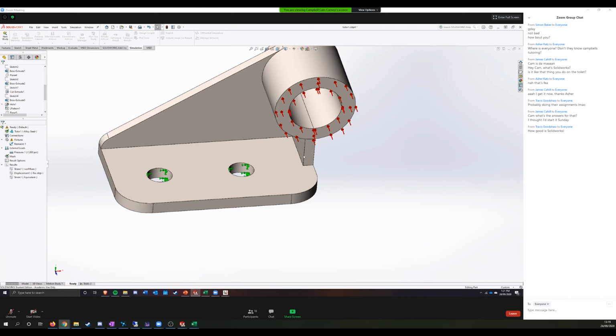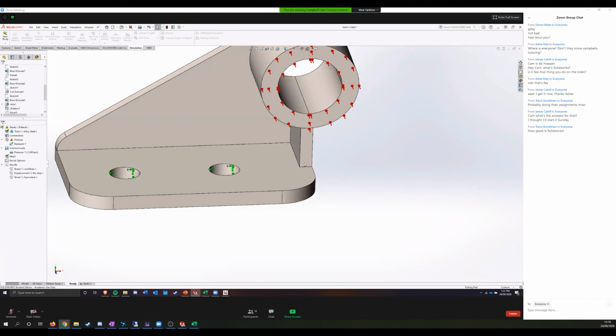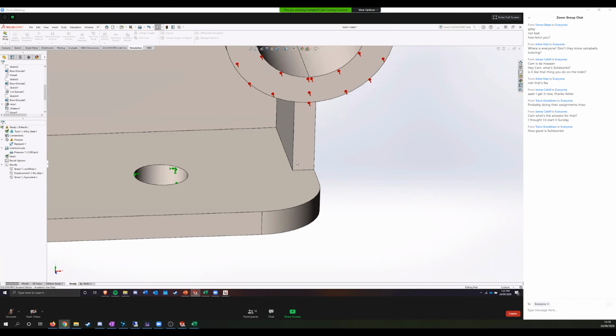So this is again going back to that stress equals force divided by a cross-sectional area equation. At this point here, you're worried about the particular hot spot right on this corner. Now, it may be slightly above this corner, and that's because of something called nodal averaging. It takes the nodes at each corner of the mesh, and then it averages the values at that node with all of the surrounding tetrahedrons.